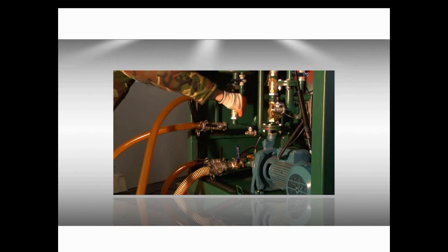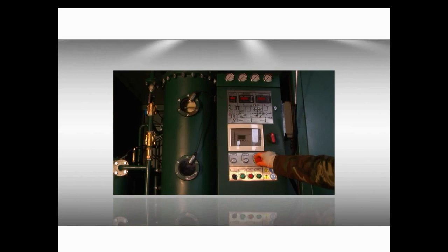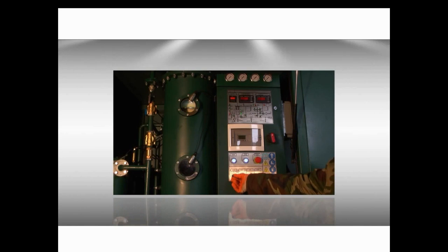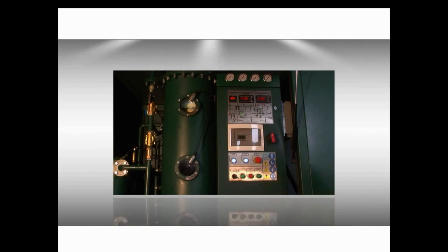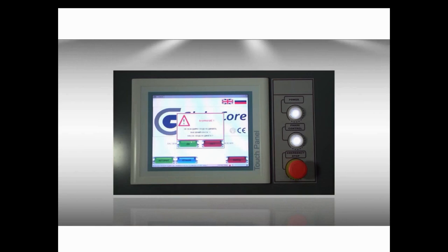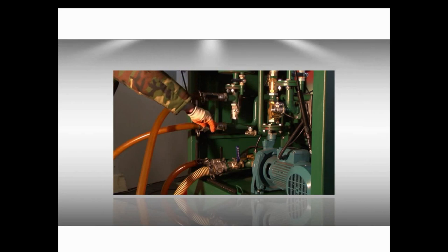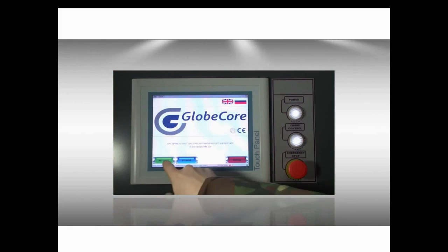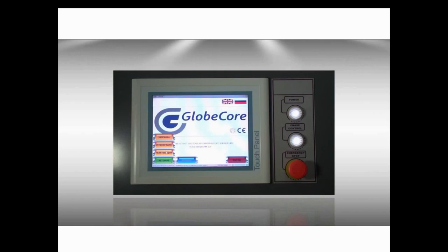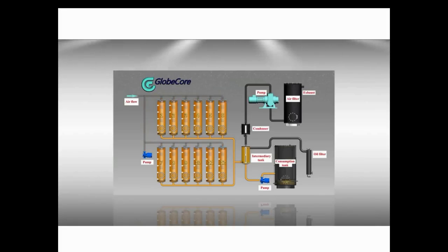Next day, oil passes through Fuller's Earth again, but this time starting with 0.07 acidity. It means that now we can do half of a transformer. As soon as Fuller's Earth gets saturated, we reactivate it, and meanwhile the degasser continues to mix. Oil acidity is reduced to 0.04, but acidity in windings is 0.07. Due to the equilibrium, oil in the transformer sucks acidity out of the insulation, and so on and so forth.